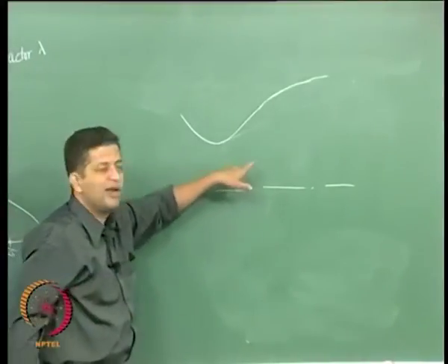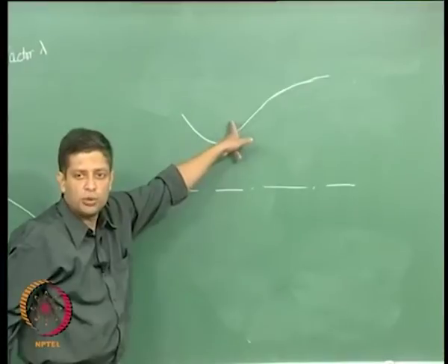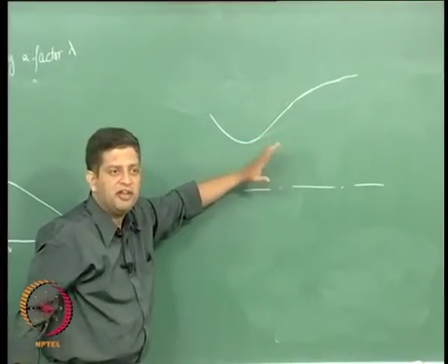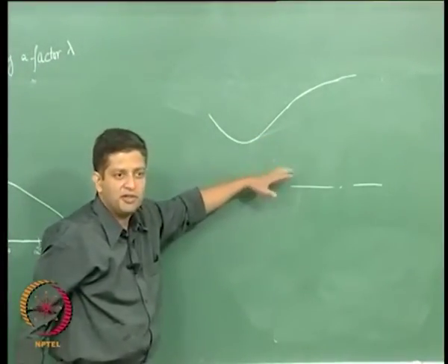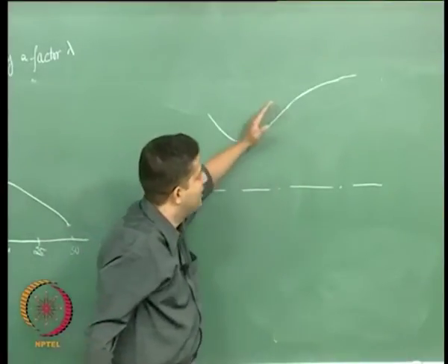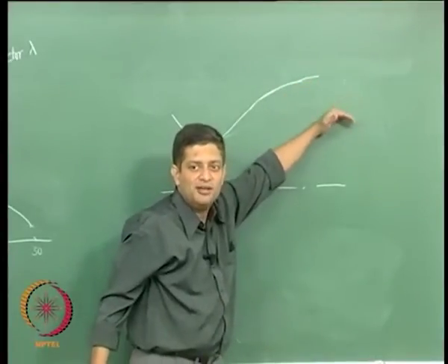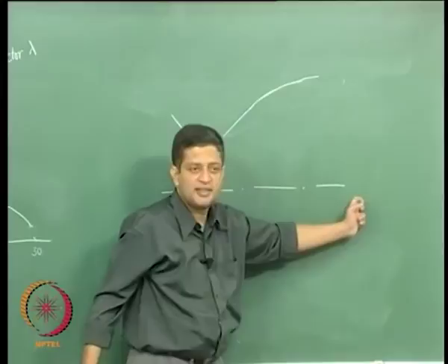Essentially, what is done in the bell nozzle is we increase the angle after the throat, right. We make the flow turn through a very large angle after the throat, and then make it go as parallel to the x axis as possible.